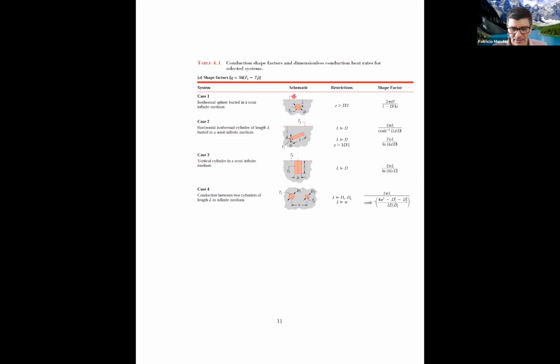Isn't this amazing? And here you have the formula. This formula is something that neither you nor I will be too quick to derive. This is small enough that it is less than a PhD. But you need to know what you're doing, right? And the good news is we don't need to know. We just need to know where to find this formula. And for this geometry of a sphere under the surface of a large, semi-infinite surface, this is the shape factor.